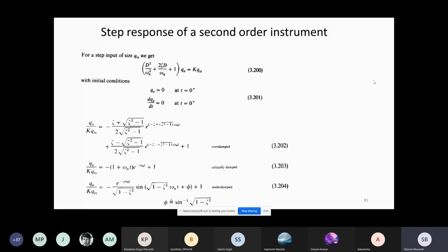You see that 1 is there. So it is an overdamped system. That means it is not oscillatory. It will always be less than 1 as t keeps on increasing. And when t is very, very high or t is infinite, you will see that the first two terms will die out, because you have t there, and both the terms are e to the power minus something, because root of zeta square minus 1 will always be less than zeta.